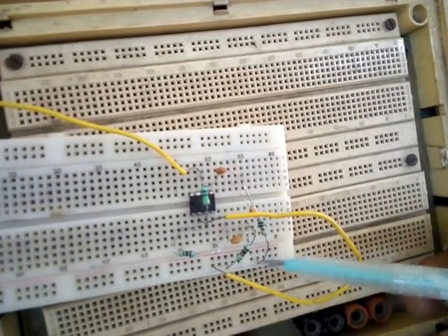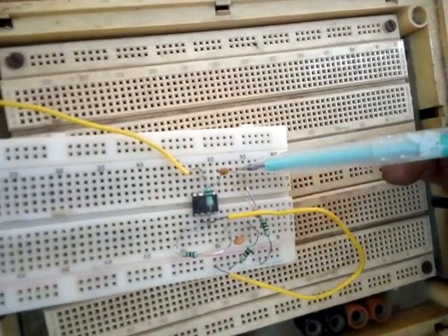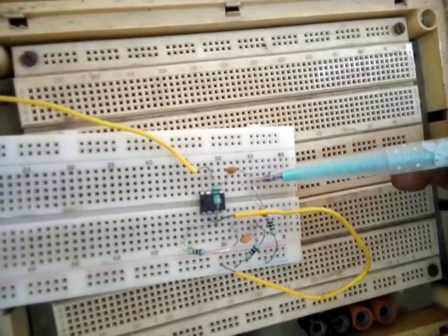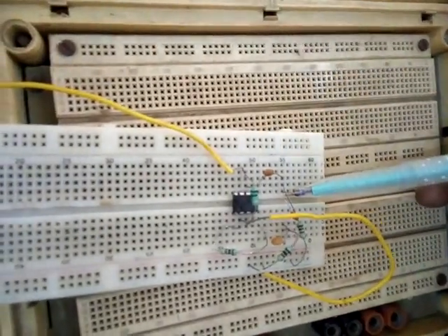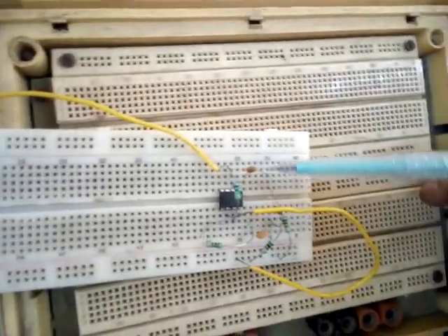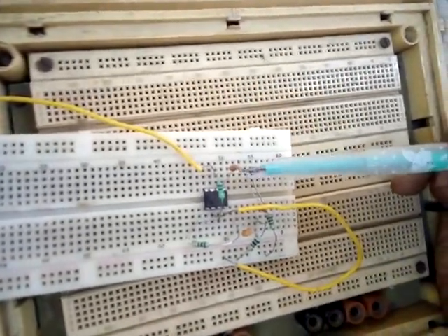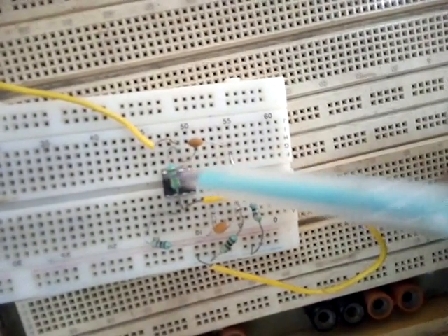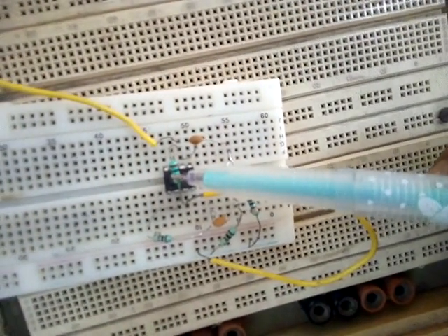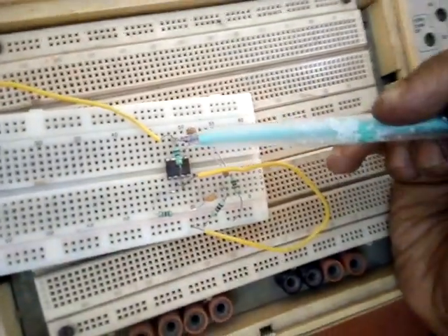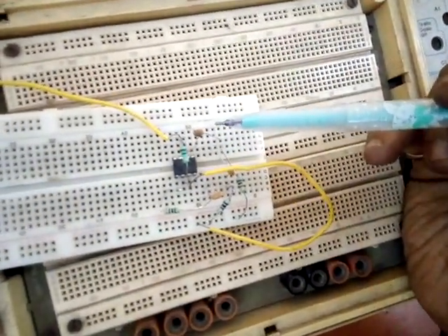Next, C2 and C3 are connected to another point, and there is also another resistor, that is R3, which is connected to the ground. C3 is connected to the output, you can see it, this one. And this is the feedback resistor, that is 100 kilo ohm, which shorts pin number 2 and pin number 6. So this is the circuit.